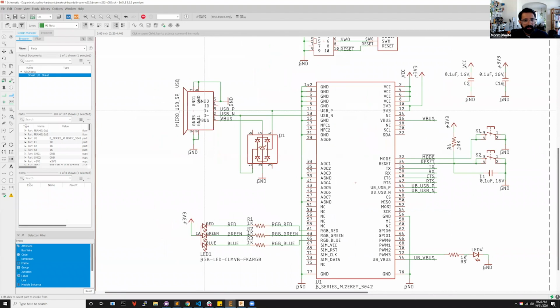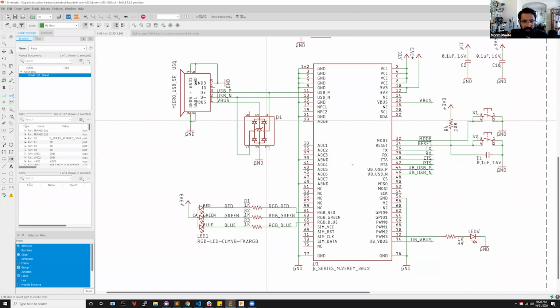We have a USB interface for the main MCU. So say if you wanted to debug over USB over a serial, or if you wanted to load new firmware, all of those fancy things can be done over USB. Every time you're exposing a connector to the external world, it helps to have ESD protection of some sort. In my career at Particle, we have never had a case where a USB blew out the hardware, but you never know what circumstances you're working in. We have been using these things within the lab, so we don't have to worry, but it always helps to add. Remember, adding these parts like footprints are free, but board respins are not.